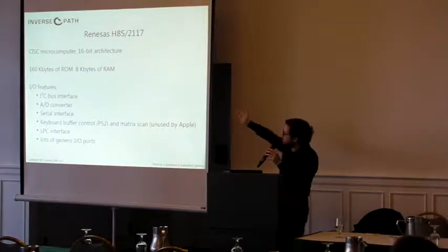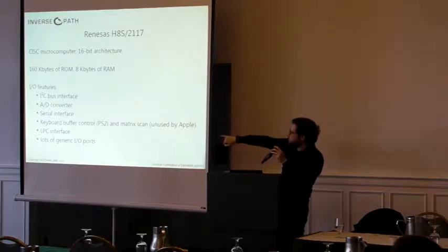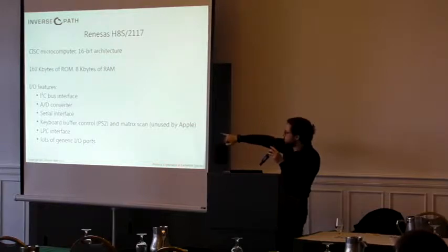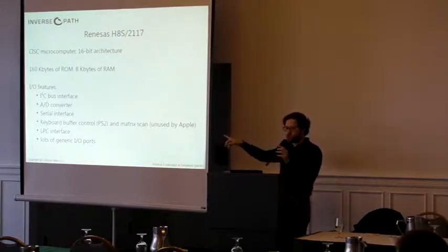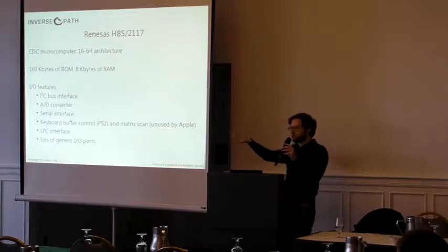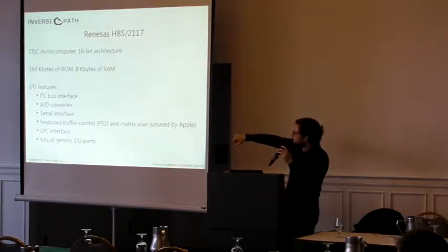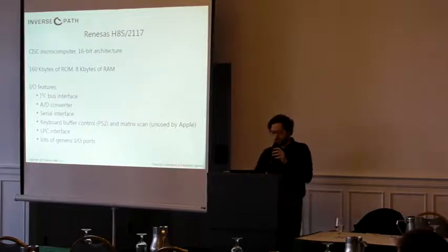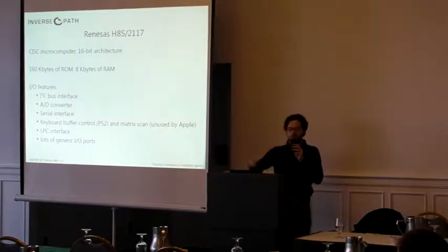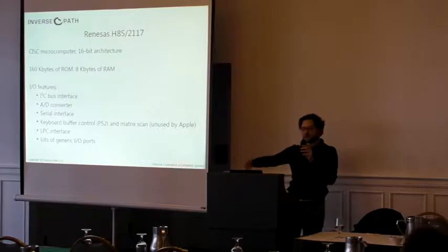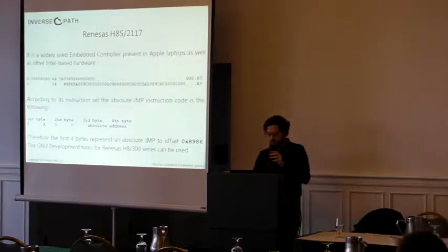It has an I2C bus interface, an analog to digital converter, and a serial interface. It can implement keyboard button control, which is compliant with being used as a keyboard controller, and matrix scan, which is, however, unused by Apple. It is used in this fashion on Lenovo ThinkPads, but not by Apple. And it has lots of generic I/O ports, which is compliant with having to control the different fans and so on.